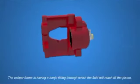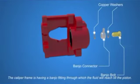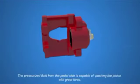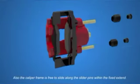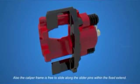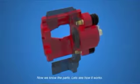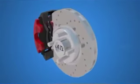The caliper frame has a banjo fitting, through which the fluid will reach the piston. The pressurized fluid from the pedal side is capable of pushing the piston with great force. Also, the caliper frame is free to slide along the slider pins within the fixed extent. Now we know the parts, let's see how it works.